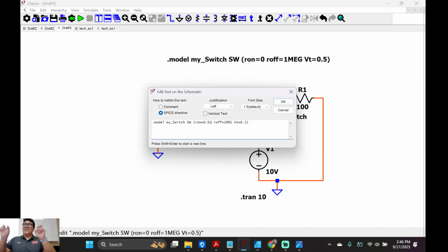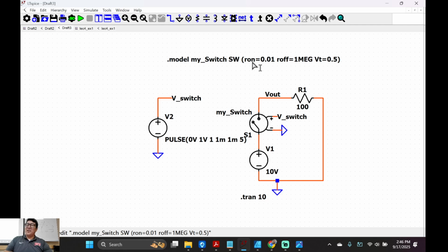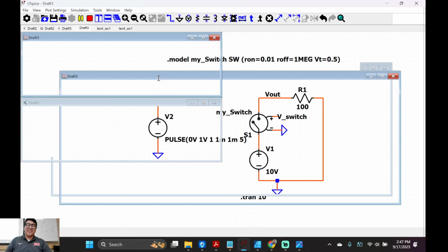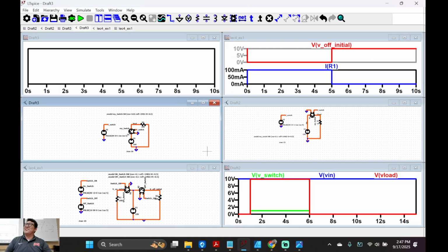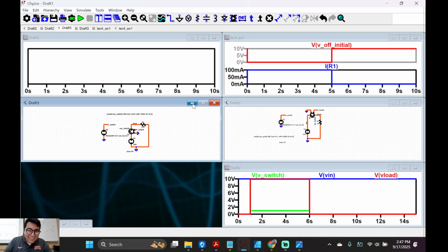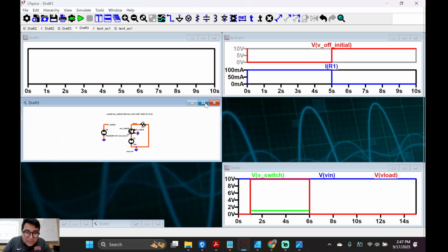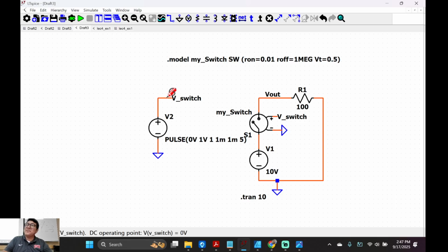So we're going to have to feed it some type of parasitic resistance. Does that look good? Our on resistance, so when it's closed, is a very small resistance, like a wire. Our off is going to be a big fat resistor, like an open circuit. Nothing's going to go through that resistor, right? Let's run this. Oh yeah, I have other circuits I'll show you. You like these little previews I'm showing you? So here's our switch right here. Let me grab this. This is Model 3.